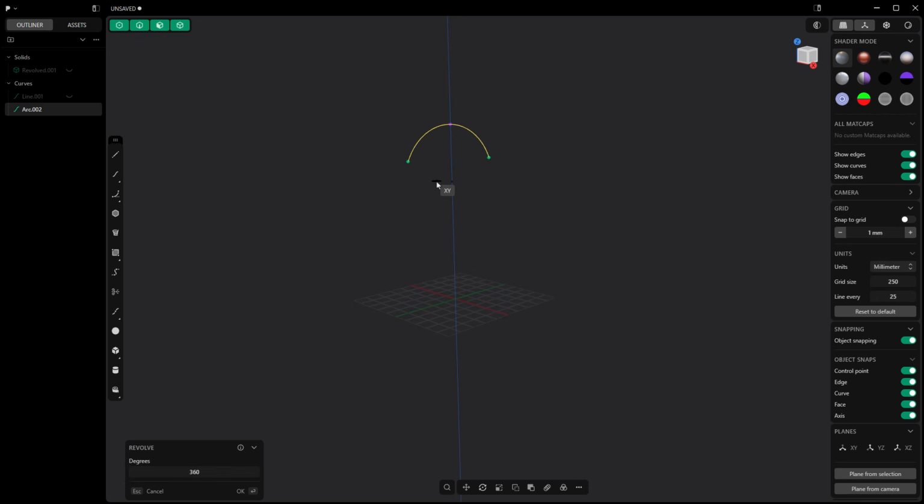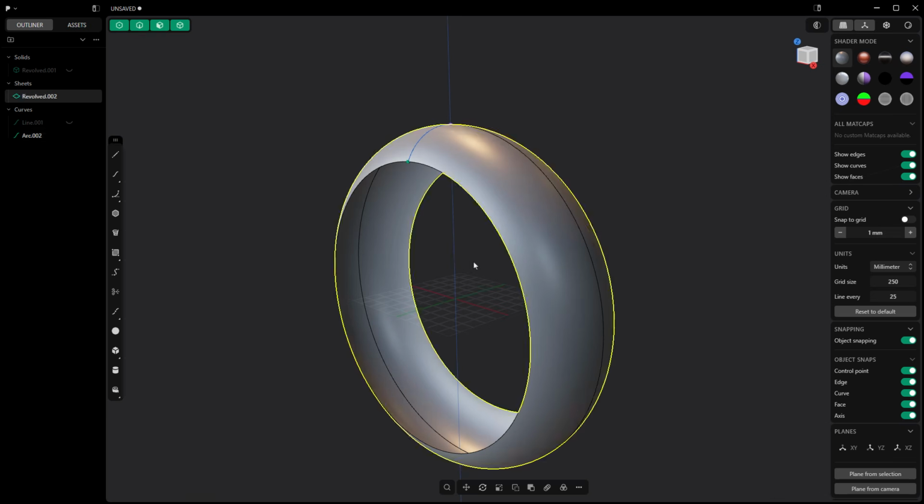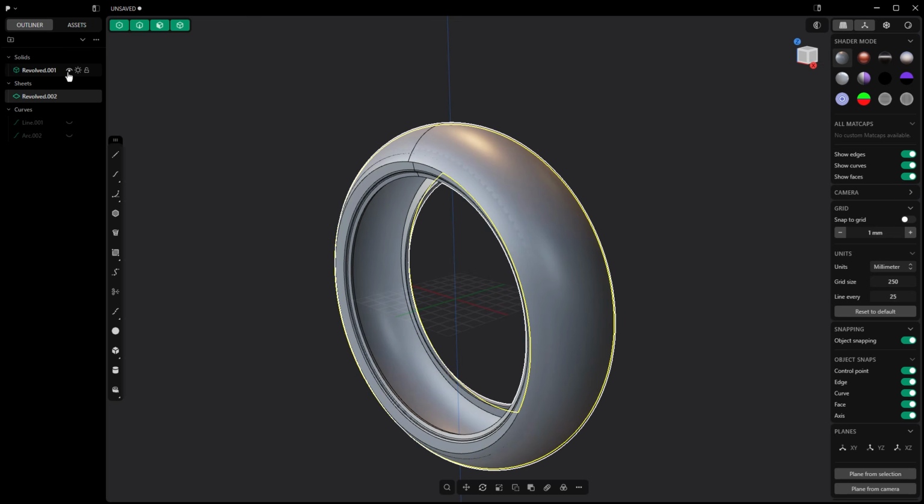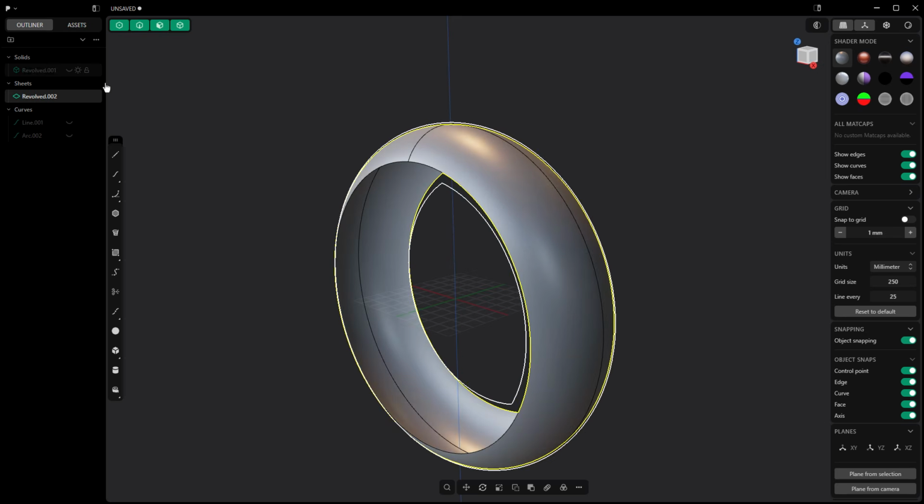So revolve this time is going to produce a surface for us. Again, click on the y-axis, then hide our curve. This surface is going to be exiting wider than the tire, wider than the solid, but it's going to be inside, which means when we create our solid geometry, our tools will go into the solid body deeper in the center, and they'll fade away on the side. That's why we're doing this: we're basically creating that cut surface.